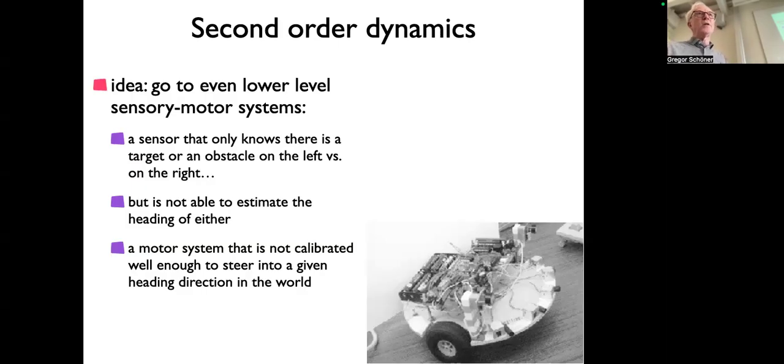Our goal at that time was to go even lower, to use very, very quick sensor information about everything. So we had, as a challenge, only these distance sensors. These are the distance sensors that are on that later robot that you barely see. Down here, this long thing is just a rubber tube around an emitter. So it emits infrared light. And then this little box is the receptor that measures the amount of reflected light. And there are 5 of those.